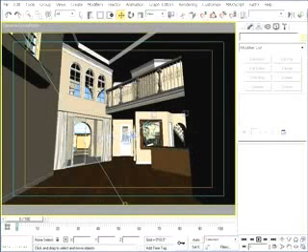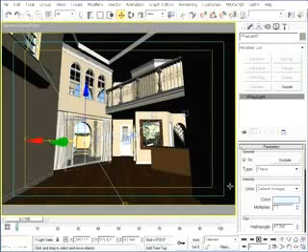So as with the last light, I've already created this light and assigned an intensity value. For this light, I assigned an intensity value of 7.5, which is halfway in between 10 and 5, which I assigned for the first two sets of lights. And I assigned a value of less than 10 because the opening is oriented at a 45-degree angle to the sun, so less skylight is coming in for that reason.